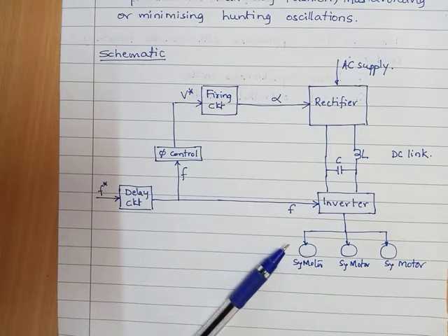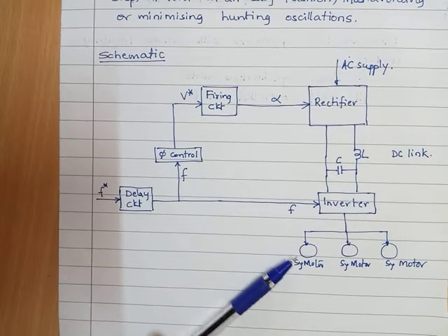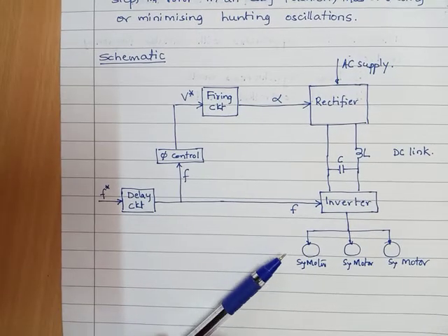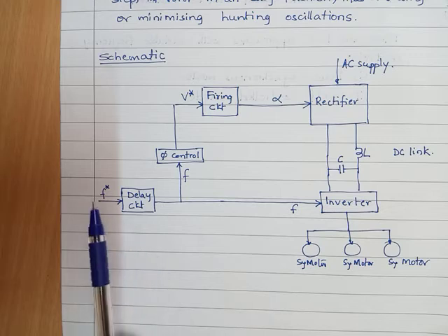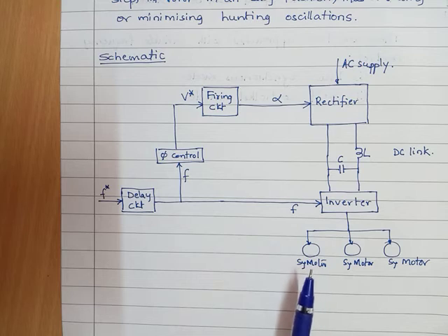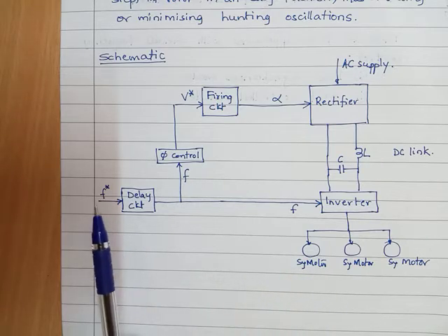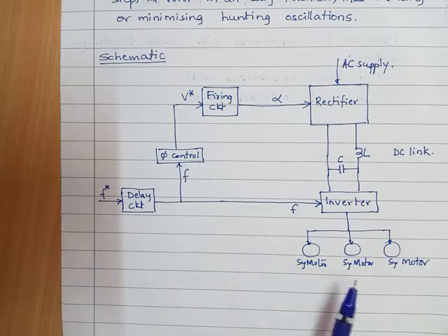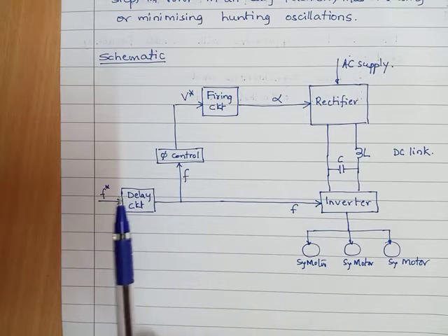It will not happen that way, because this motor is an electromechanical system, whereas changing the frequency is a purely electrical system. We know that the electrical system time constant is very small, whereas the electromagnetic system time constant is high. The motor requires more time to respond. Hence, there is a need to change the frequency keeping this in mind. That is where the delay comes into the picture.